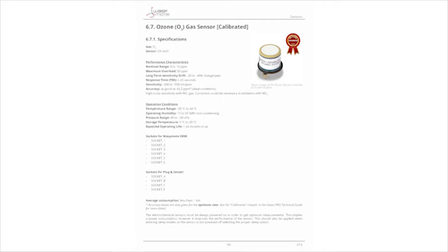The sensor loses accuracy as time passes. The manufacturers say that after 12 months, the accuracy is not enough and you must exchange them. And it is not possible to recalibrate the sensor. So the only way to assure the accuracy is to exchange the sensors often. The particle sensor is not electrochemical, but optical. It's enough to clean the lens and the fan sometimes, and you can keep it a long time if you are reading coherent values. Let's check the most important applications.